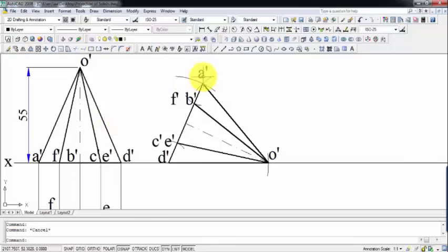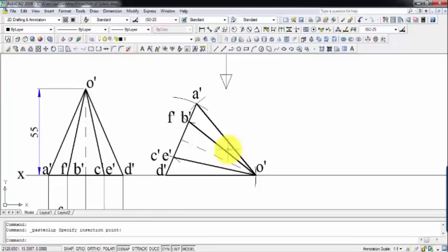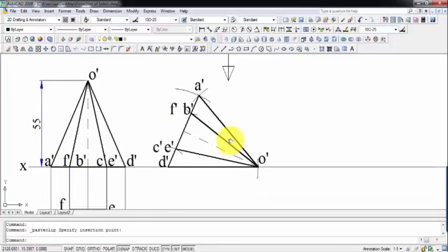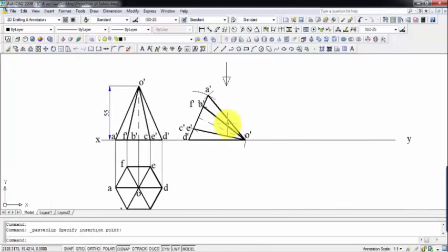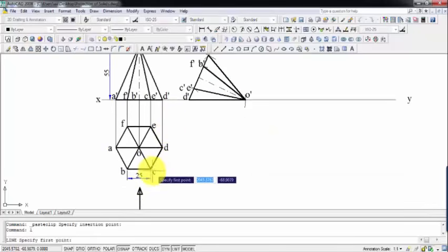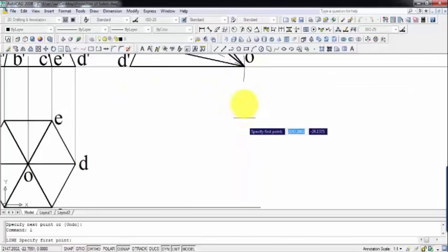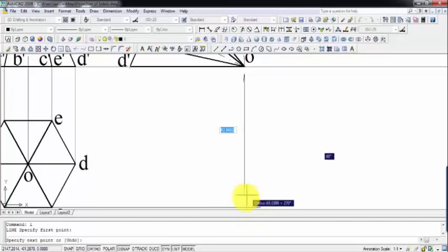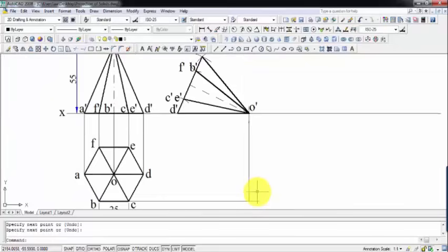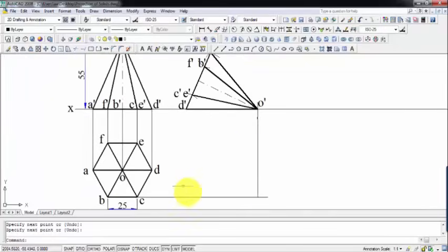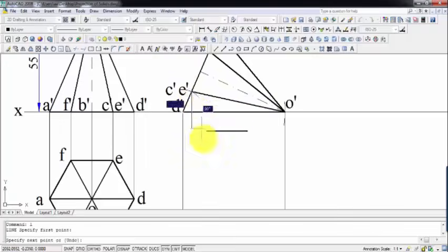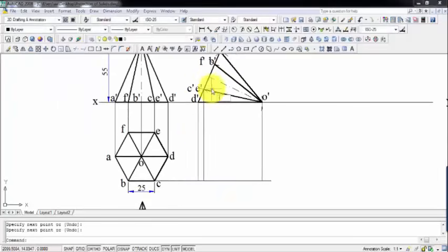Now the next step is to look at this object from the top. Now we are going to create this corresponding top view, and let's see how this object looks. For that, this is a small construction that I'm going to do. Let me draw this line, an absolutely horizontal line. You can do so with the help of a mini drafter or a ruler scale also. Let me draw this vertical line. So this is my boundary in which the corresponding top view is going to be created. Let me drop vertical lines down below, something like this. Alright, that's it.